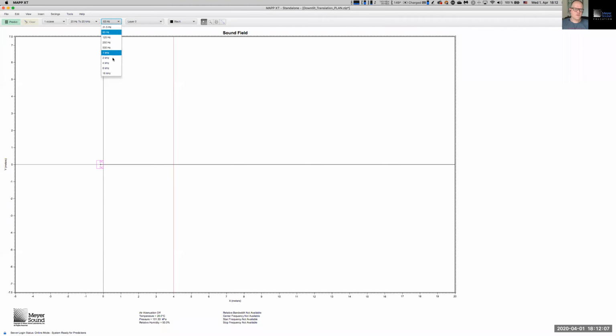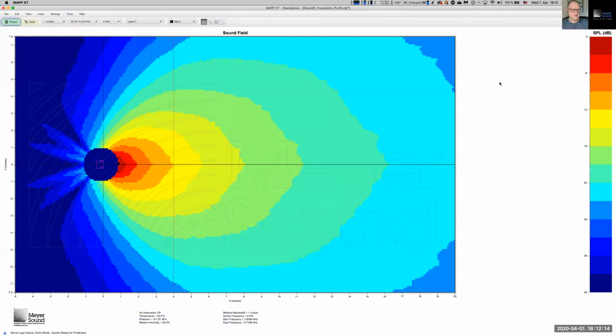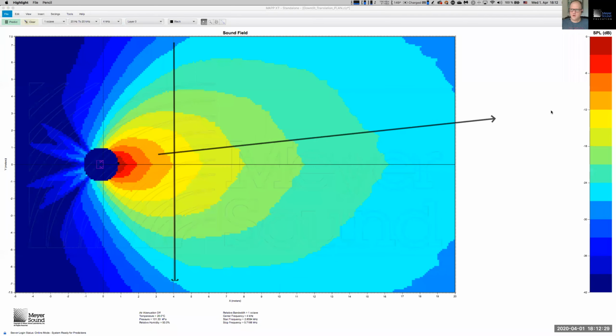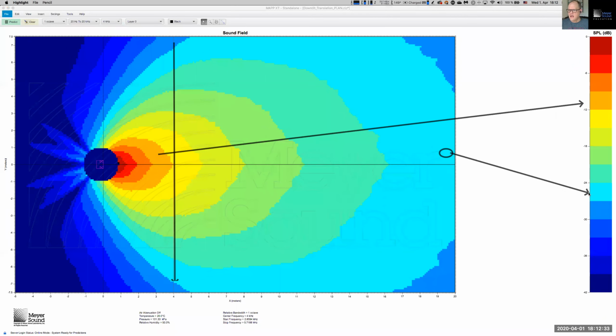If we're gonna look at the same frequency, which will be 1 octave centered at 4 kilohertz, this is the picture in plan view. And if I look at this, knowing that the first row lives over here, it looks like we're killing the people in the first row. I mean, just look at that color. If we judge a book by its cover, this would suggest that we're looking at this color, whereas in the back of the audience, we're looking at that color, and that is about 1, 2, 3, 4, 5 divisions of 3 decibels. That's about 15 decibels of difference in level.